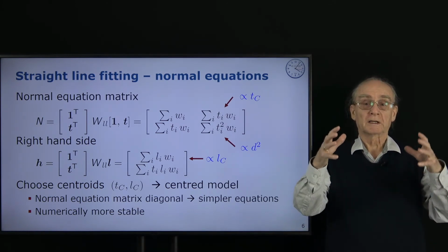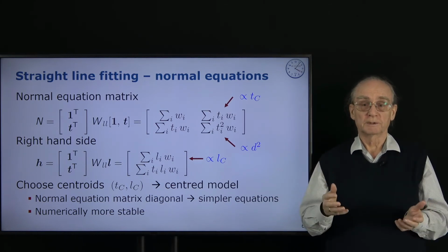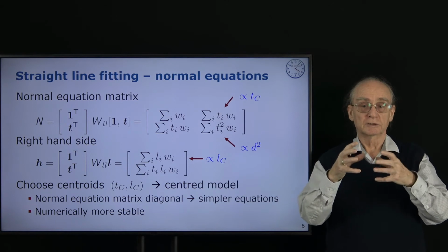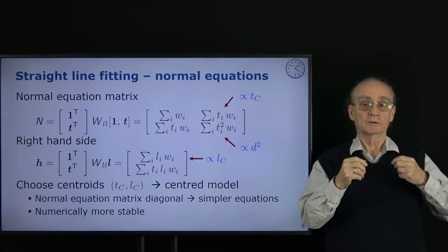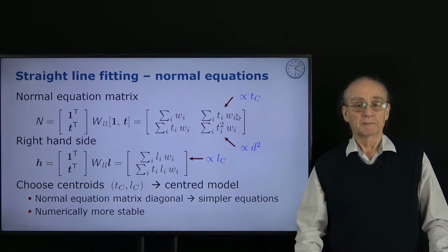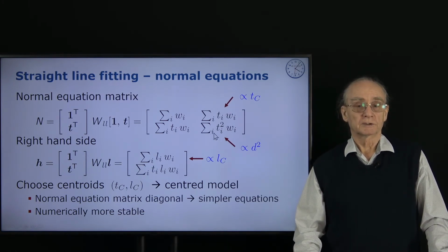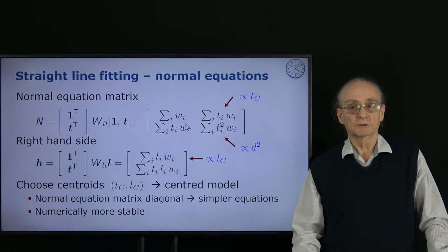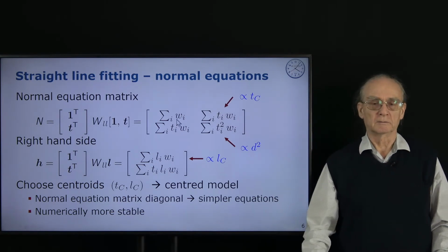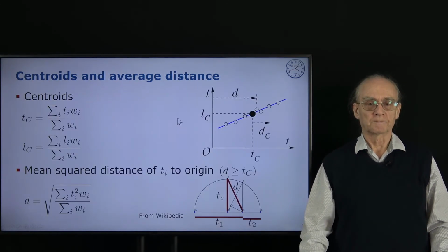And if you have a small area, let's say 1 kilometer, that means that you want to have translations and rotation in this small area, and you refer all of these coordinates to a very far point, then probably this equation system will be extremely badly conditioned. So it's reasonable to work in the local system, which is anyway meaningful from a practical point of view.